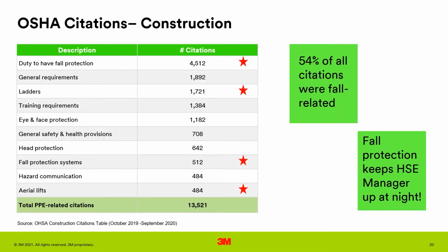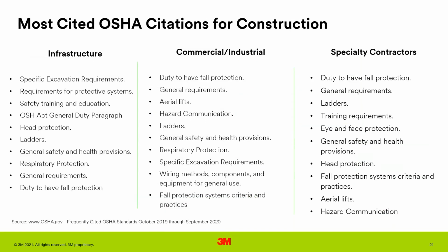You can see also on this list that eye and face protection is there, as well as head. So all of the things that we're going to talk about today to help to keep those workers safe. So these are the things that keep that construction safety and health professional awake at night. When we consider the other further breakdown, within infrastructure, commercial, and specialty contractors, you can see that they all have duty to have fall protection as an issue, but where it falls in the pecking order is different for each of these types of groups.